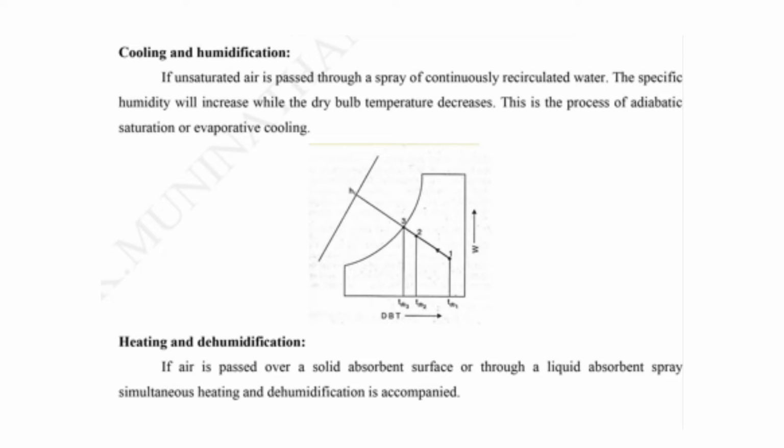In the bottom figure is shown the psychrometric chart of the cooling and dehumidification process, where the enthalpy line will provide the different dew point temperature values, and then we can find other characteristics from the psychrometric chart at the midpoint of the dry bulb temperature and the enthalpy line, and the W value is also obtained from the vertical axis.